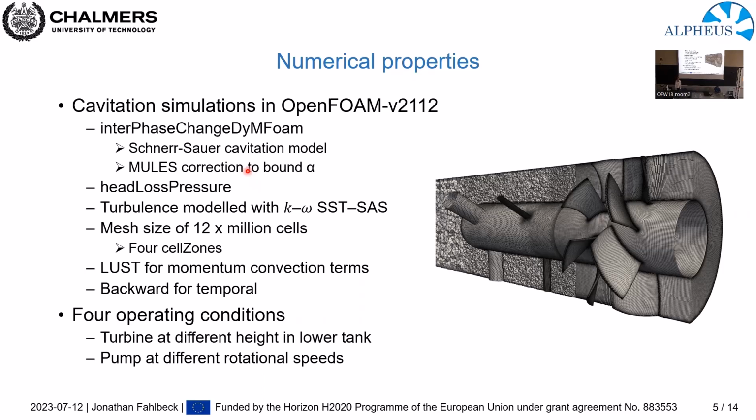And I just want to comment that if you use this solver, please use the MULES corrector. I'm saying this because one of our neighboring departments at the university have developed their own solver model, and in their solver they don't need to use this MULES correction. So initially I did not use this MULES correction, and that made the simulation blow up. So if you intend to run cavitation simulations, use the MULES correction.